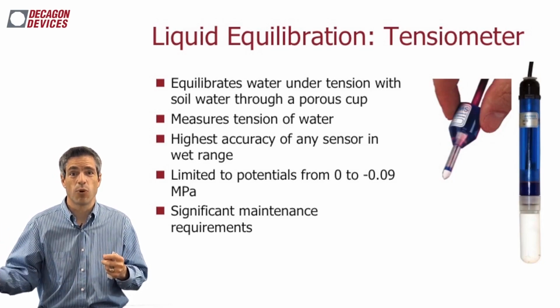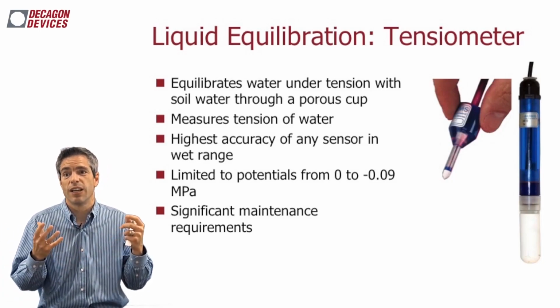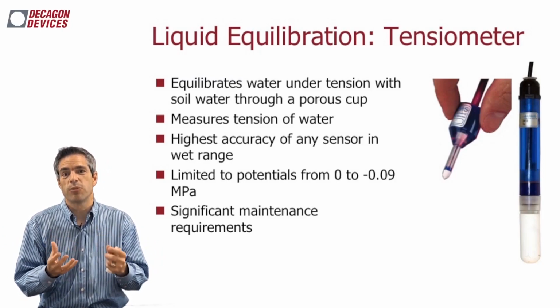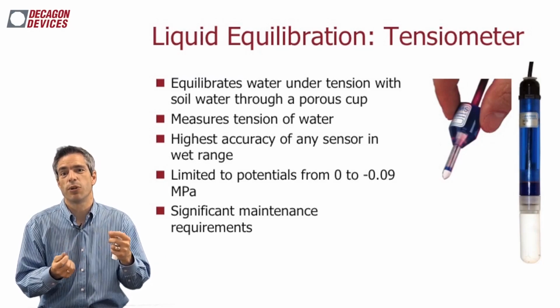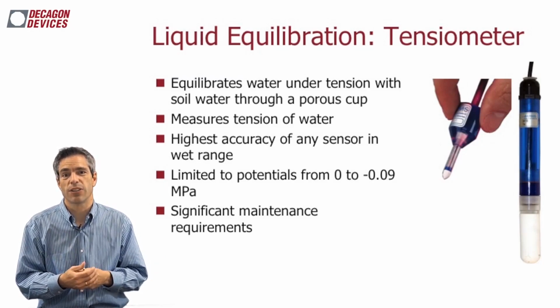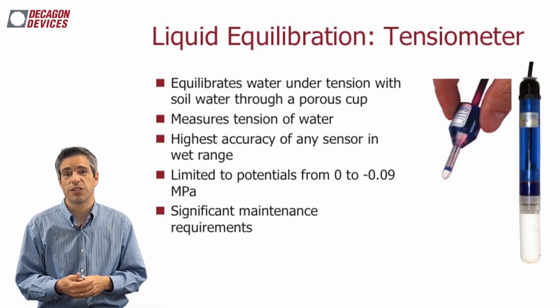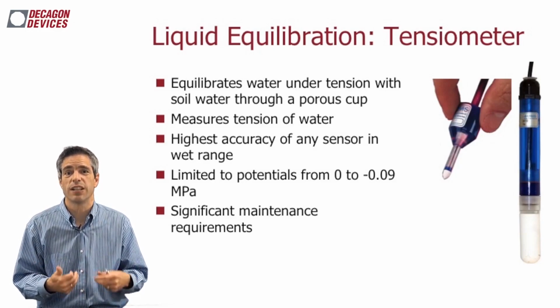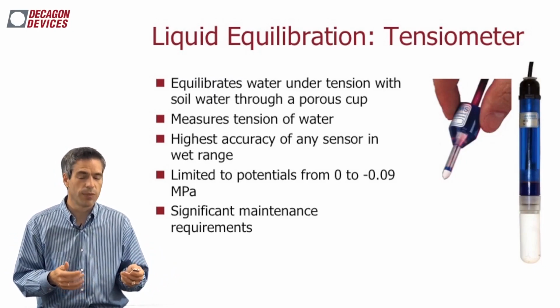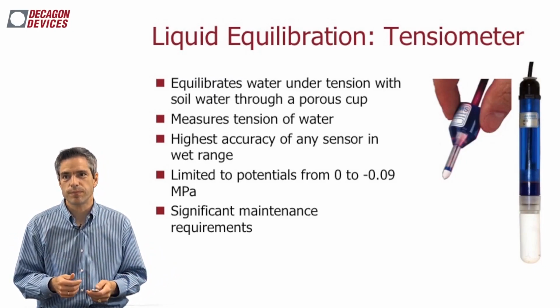And the final point on the slide where we say significant maintenance required, that is what I'm talking about, because you have to go in and you have to refill these tensiometers with water and put them back out in the field or in the lab. And this actually takes some time. So great technique, has its limitations. We just need to know about them. We can deal with them if we know what they are.